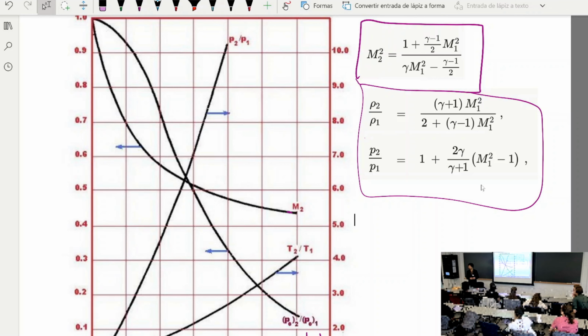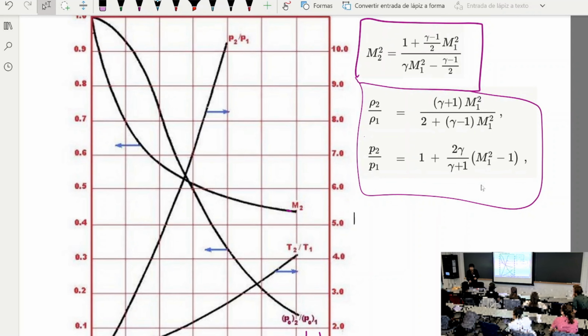Now, velocity over. That's right, but the key here is that the speed of the shock relative to the ground is exactly the speed of air upstream of the shock relative to the shock. Does that make sense? Because the air before the shock arrives is stationary, right?